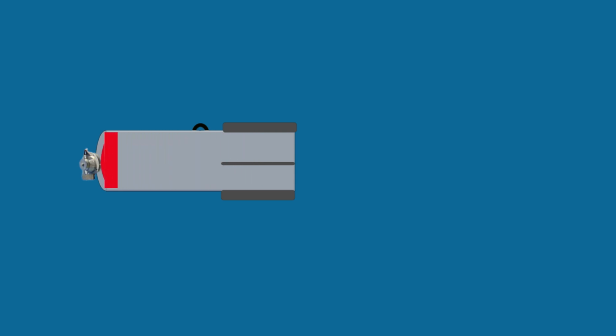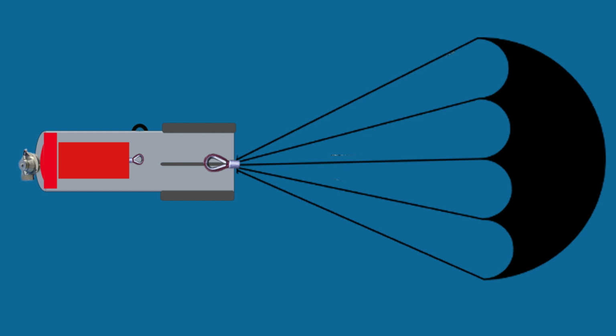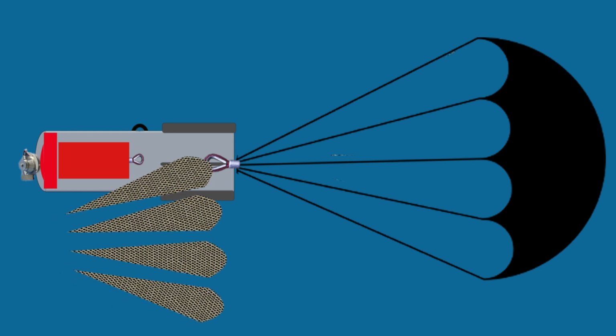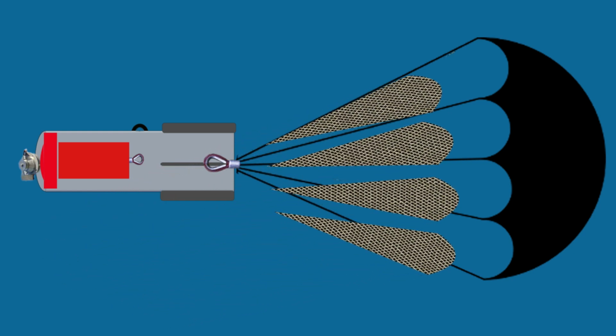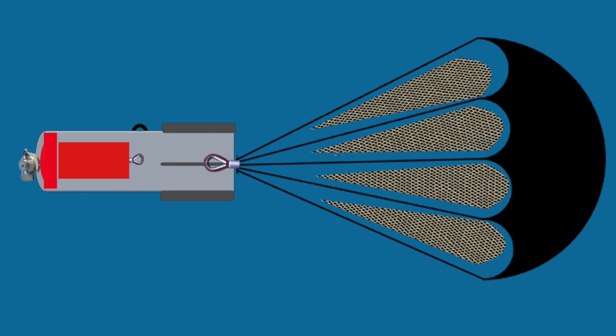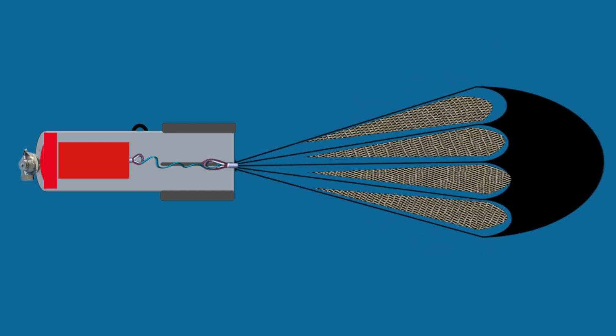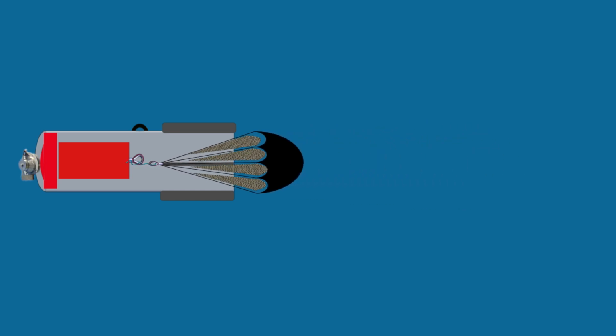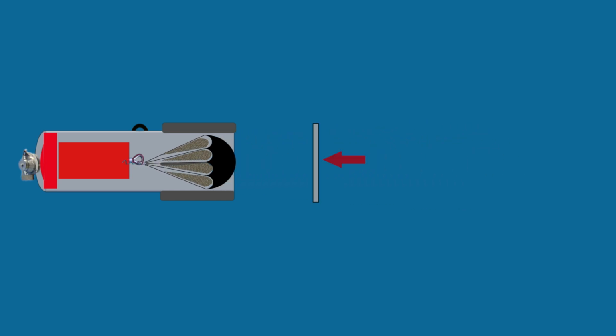Behind the explosive pad there is a flare composition or candle. Behind the flare composition, there is a parachute. In between the parachute rope, carbon fabric or mesh is stitched. The carbon mesh is capable of reflecting the electromagnetic rays. A fireproof rope is attached in between the candle and parachute. The complete parachute along with the carbon mesh is folded and kept inside the container. And at the last, this is a lid.